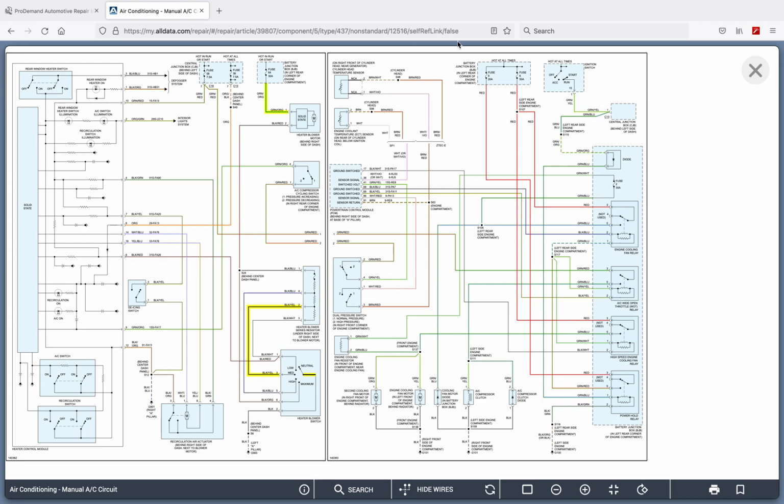One, it's really inclusive, includes a lot of things in a diagram, but the most prioritized thing for me as a technician and a technician educator is that we have the inclusion of interactive features. Sometimes when we're looking at a factory diagram, we can go, what color was that wire again? Well, I know if I highlight this wire and it says it's black and red, I can follow this black and red all the way down to at least a splice point.